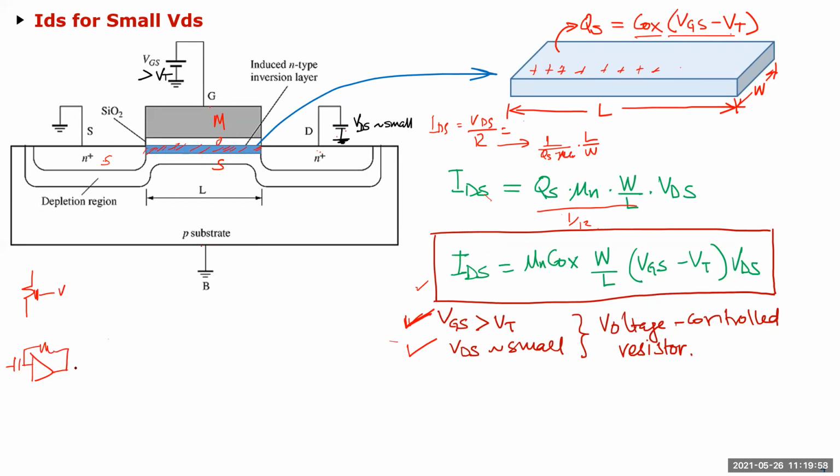So like this is a high pass filter, and let's say I want to change the corner of this high pass filter. I put a MOS device here in linear mode, and I control this gate voltage, then I can control the corner of the bandwidth of the filter. Okay, so we do use this as a linear resistor in analog design actually. Okay, so that's the first condition.